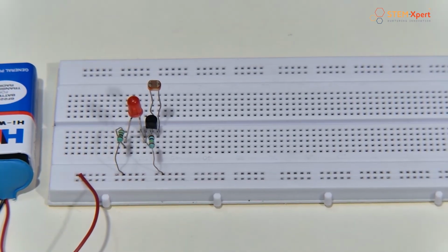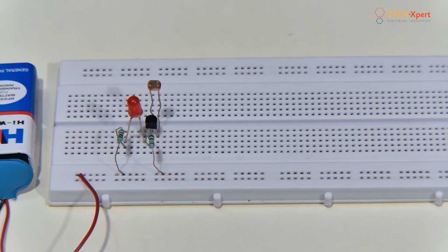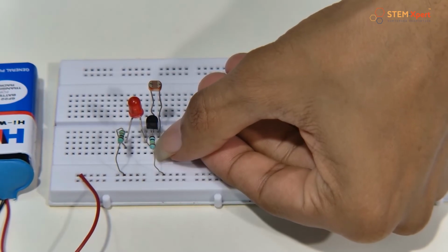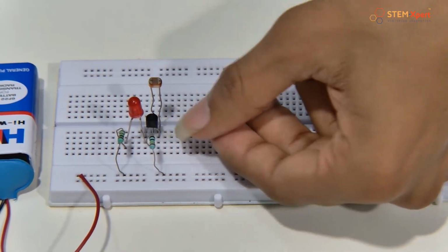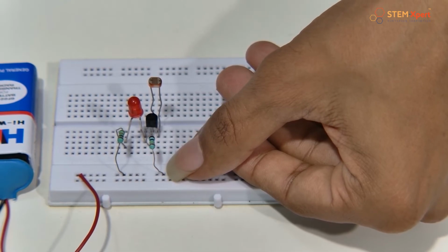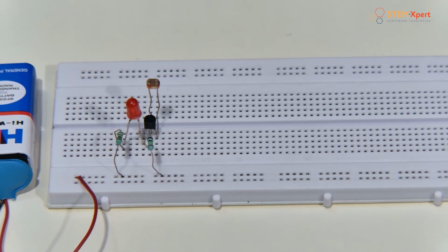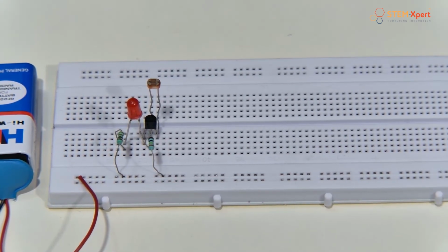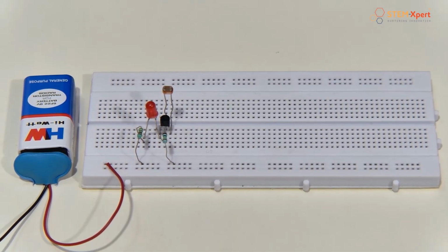Now as you can see, I just connected my 100K resistor along with the base terminal of our transistor, because we know that according to the breadboard in the B part, each and every point will act as base and this one is our emitter. So we can simply connect the 100K resistor along with the positive, that is the A part of our breadboard, and the other terminal to the base terminal of our transistor like this. So now your turn. Take your 100K resistor and connect one terminal along with the positive part of our breadboard and the other terminal to the base part of our transistor. I hope you have completed the connection of the 100K resistor.